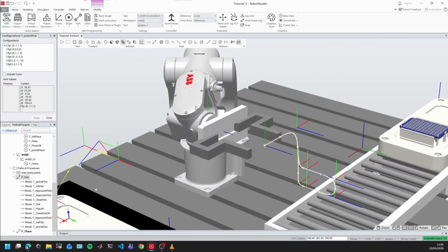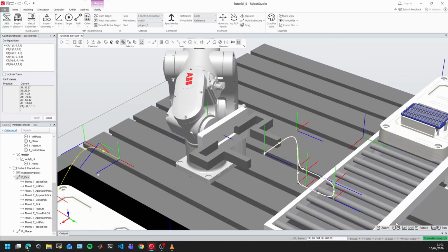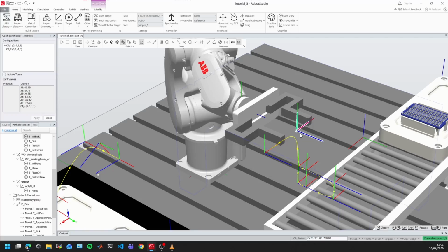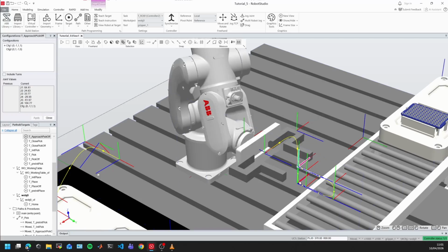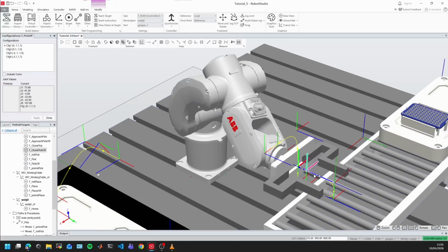Like I said, one of the tricks in this software is to look at a special part. For example, I look at the logo. You can look at anything else, but look at a special part, like the logo, and try to move it the least amount possible when using linear movements, not joint movements. For example, small rotations only.